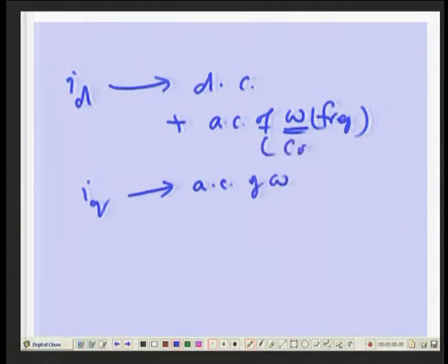So, this will be a cos component, this will be a sin component. They are shifted. So, it will be the DC plus fundamental. I want you to appreciate this because these are little concepts you need to assimilate at this point in time. So, if you neglect all the things immediately after short circuit, ID and IQ will be having a DC plus sin square component. Now, you will go back, what happens under normal steady state operation?